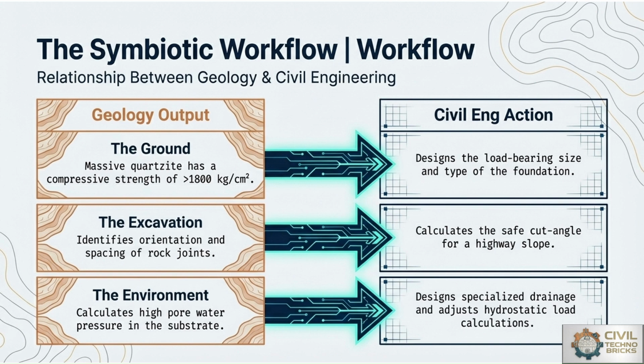Here the geological information directly influences engineering decisions, where the rock strength determines foundation and structural design requirements. So the relationship between geology and civil engineering is the most important parameter from the excavation point of view also. Excavation methods depend on rock mass characteristics and discontinuities in it. Groundwater conditions influence drainage systems and hydraulic structures. Geological observations are converted into engineering solutions during project planning.